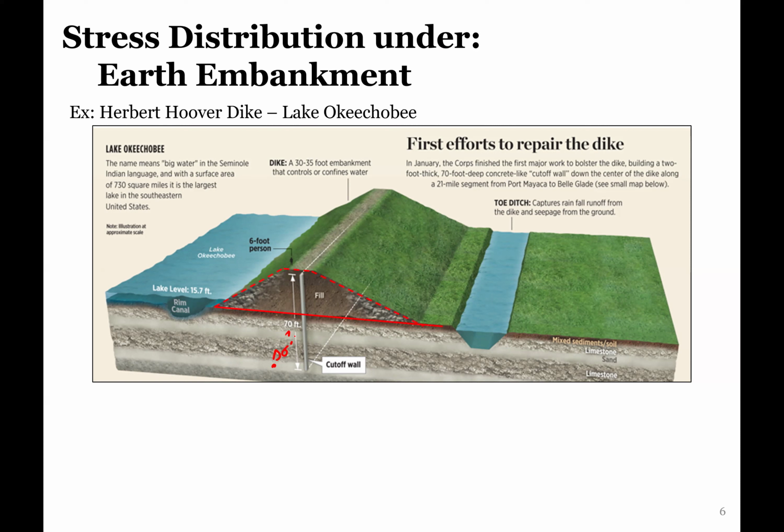So this type of shape is very common in geotechnical engineering, a pyramid shape, and that's just because we can stack soil up, but in order to ensure that it is not failing, we would need to have it at this 2-to-1 slope or 3-to-1 slope, some type of slope. So we can still get the height achievement or the elevation change, but then also not have any type of failure or landslides. So this type of shape here, remember this is coming in and out of our screen. This is a 2D plane representation of it. So you take a cross section of it.